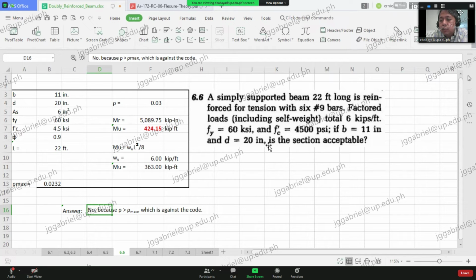I told you about what happened, the findings about the Hyatt Hotel in Baguio. The designers were professionals. They checked the design for problems, and there seemed to be none. The problem was in the construction, especially where the beam and column meet, it was too crowded.